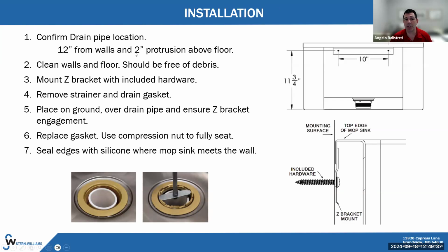One of the things we want to make sure we highlight, again, it's in the installation instructions, is that your piping is going to protrude above the floor. As you can see here, this is the floor base. This is different than some terrazzos you see out there where the actual drain assembly body is below the mop basin itself, so you're putting that into a bed of mortar and getting it to sit down into the pipe. This one, the pipe is going to protrude a little bit, about 2 inches up, which allows it to meet into the drain assembly here. That's a slight difference, but again, our installation instructions call this out and allow for a nice clean install.